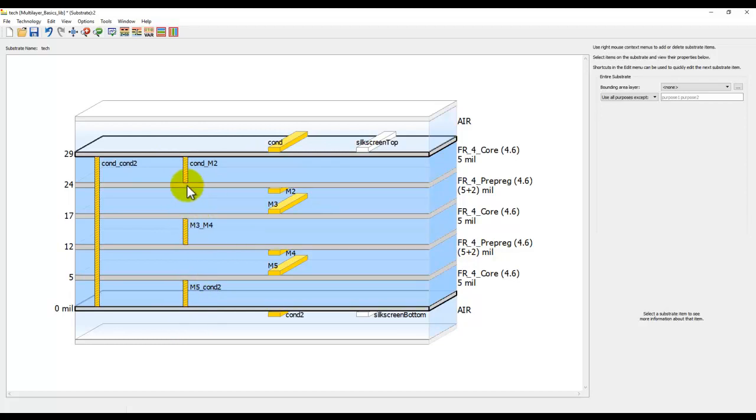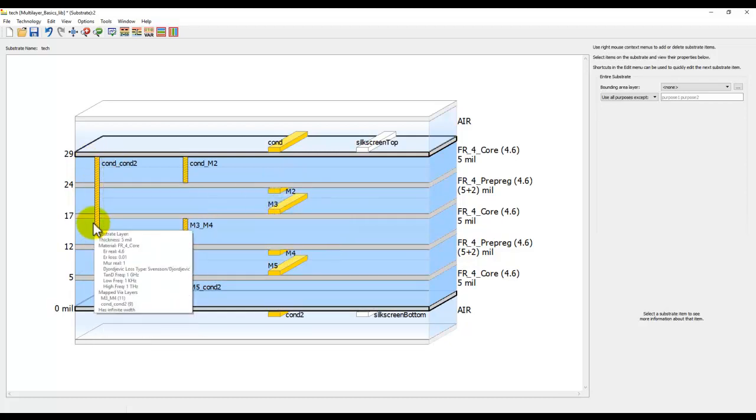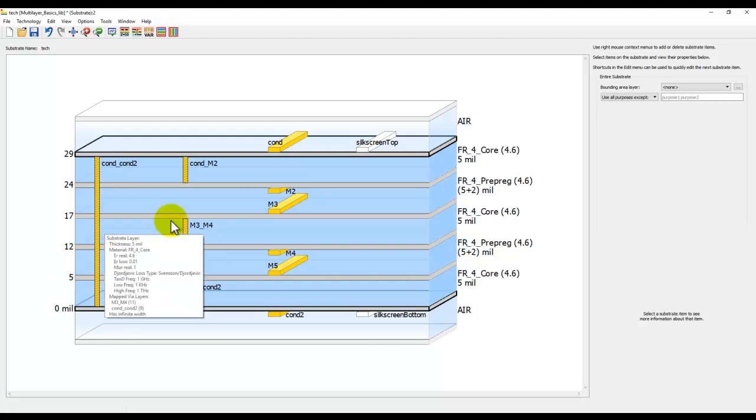If you need to map your own via layer for a certain layer, for example, let's say I want to have my via going from M2 to M3. So currently, if you don't have any via mapping, whenever in your layout design you plan to insert a via, it will get inserted with this through via template, right? So in some cases, it may not be desirable, because when you are making this connection only, then you will have this via stub on the top and that via stub at the bottom side, and this will produce capacitive and inductive effects at higher frequencies.